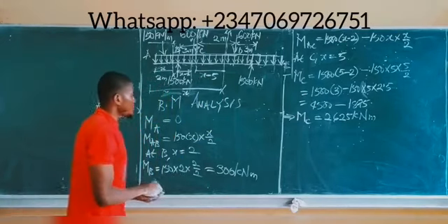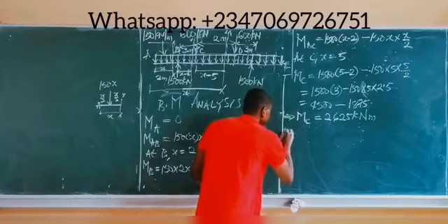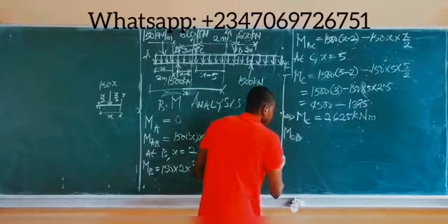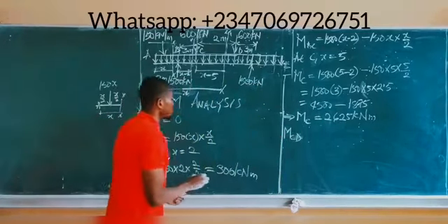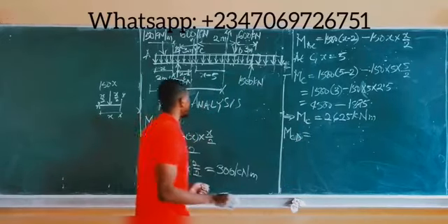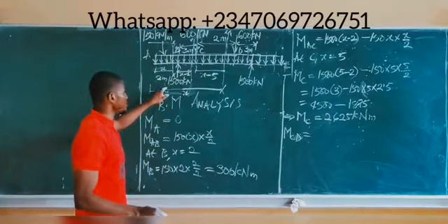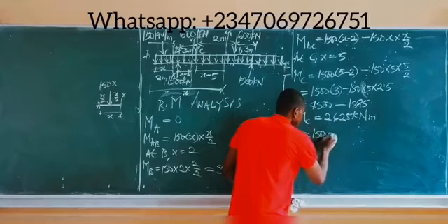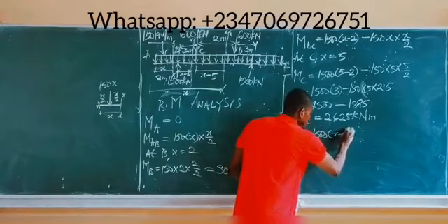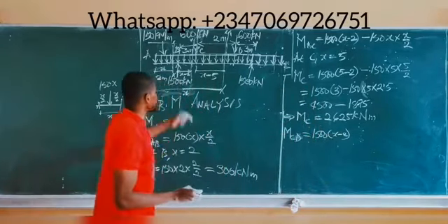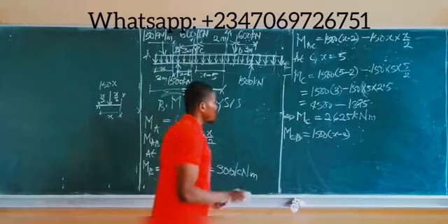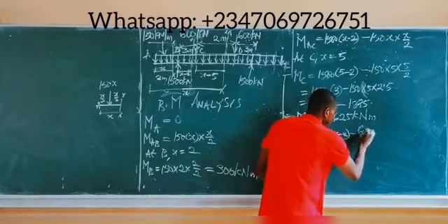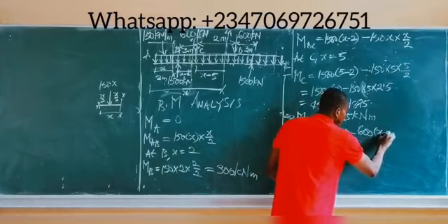So the moment of forces along CD is equal to, first of all, the moment of the 1,500 kilonewton load about that point, which is 1,500 times x minus 2. Next, for the 600 kilonewton load, since it's pointing downward, let the moment be negative: minus 600 into x minus 5.